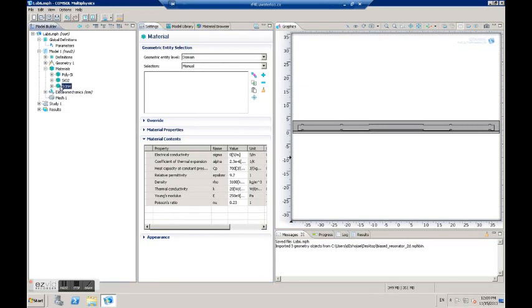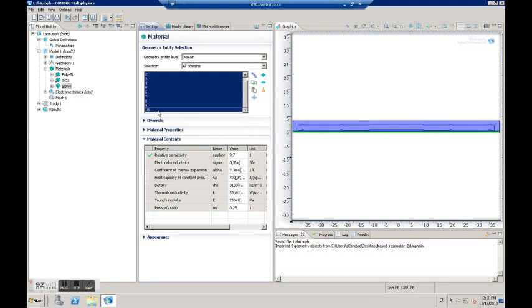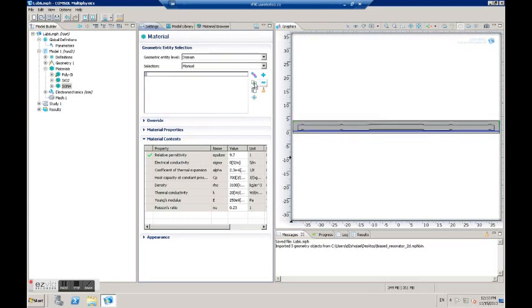In the model builder, first we are clicking on model 1 materials, Si3N4. So after finding Si3N4, select domain 2 only. Selecting all the domains, selecting the one we're interested in and removing the other domains. Now, right click on materials and choose Open Material Browser again.